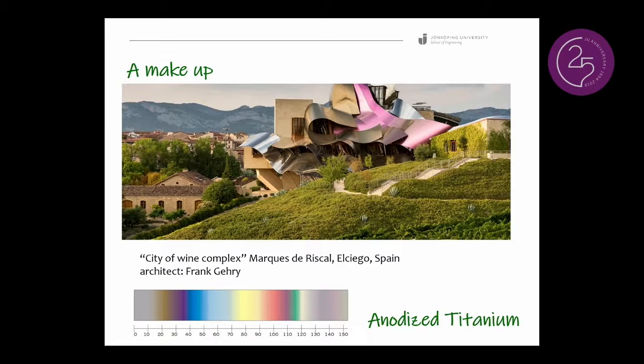The spontaneous titanium oxide has a thickness between 0 and 10 nanometers, and you see that at that scale it has practically no color. It has just the metallic color. But if we force a further increase of the thickness, this tiny layer will interact with light, giving a diffraction pattern and reflecting color, therefore developing different colors proportionally to its thickness, only when interacting with light.